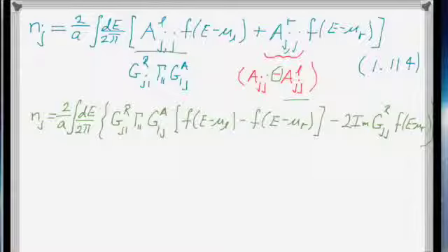So to get the electron density, you need the diagonal elements of the Green function, all of them across your whole device. You need the diagonal elements of the inverse. If you think of the Green function as the inverse of E minus H minus sigma, which is what you would do in MATLAB, you need the diagonal elements of that inverse. And this is why we spend so much time on this, because taking the inverse of a matrix is really a numerically inefficient thing to do. If you can get by with just grabbing the elements you need of the inverse and not calculate the whole thing, that's a big numerical advantage when these matrices start getting big.